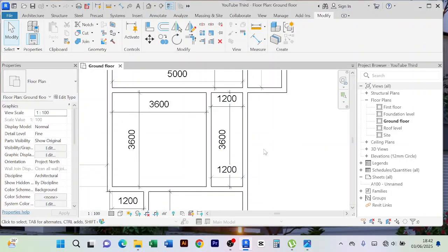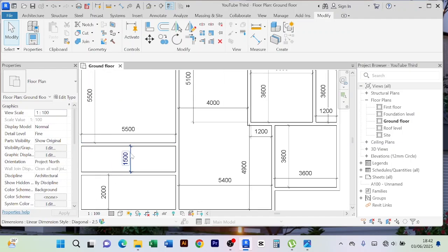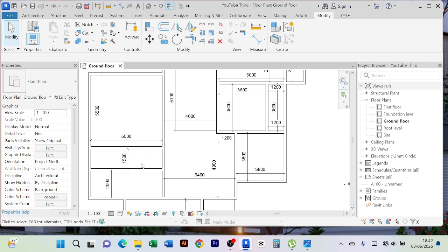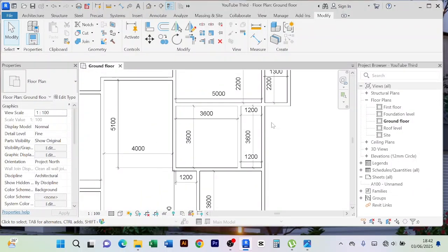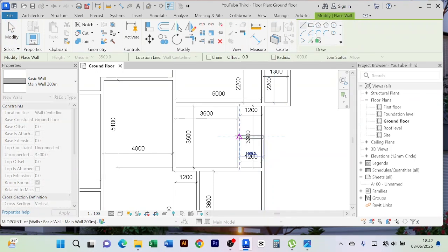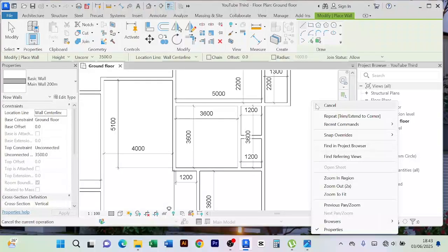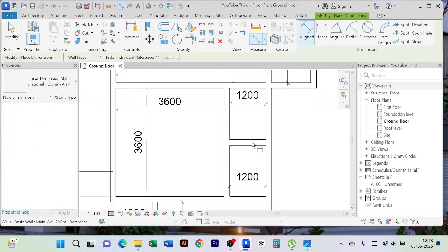Because these internal washrooms, we don't need them to really be big because we already have another washroom here which is common for anyone to access. So this one here, we shall separate it. We're going to click any of these walls, and then we come to create similar, and then we shall divide it here. So let us see, we're going to delete this. Let us see what each side has taken. This side, then this side.